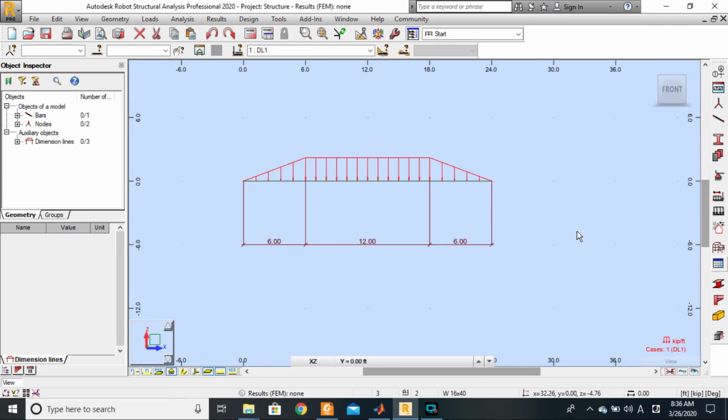As opposed to the other selection mode, which goes from left to right, which is blue but not dashed, solid lines. If I release this, they will not be selected. Reason being that this selects only all of the elements that are completely found within the rectangle, within the area of selection. We'll look at that in more detail in a different example, maybe where we'll be dealing with frames. Okay, good. So we can delete this, and to delete, you just press delete on your keyboard, and that's that.